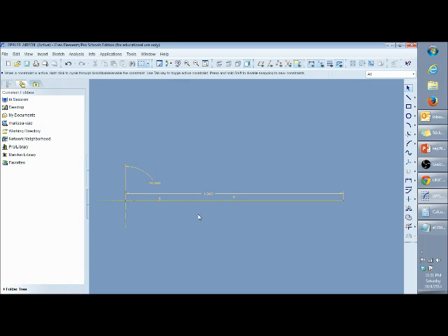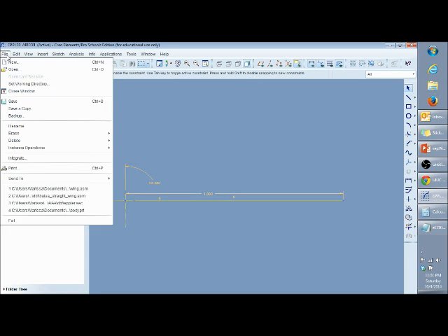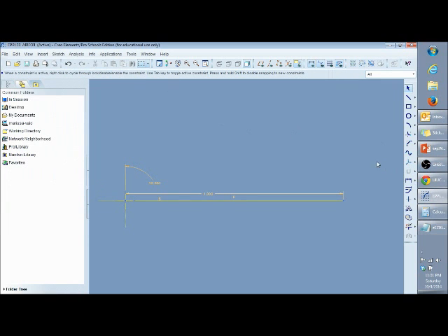The reason we're setting this line to 1 inch is that this is going to be our guideline, I guess you could say, for our airfoil. And you'll see why we use 1 in a second. So what we want to do now is use the spline tool, and you can just create any kind of abstract shape. It doesn't need a certain number of points, because we're going to modify it.